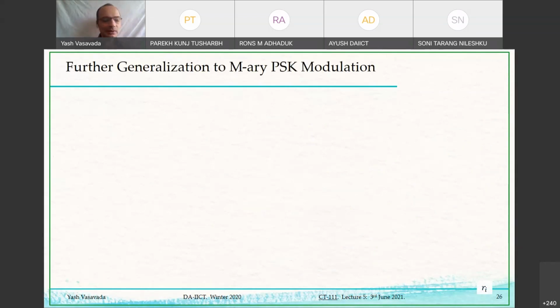So coming back to our simplified model, remember we started with BPSK. We drew the constellation diagram for BPSK. Then we went over to QPSK, which, instead of one dimensional, became a two-dimensional constellation diagram. Then we considered binary frequency shift keying, which was also a two-dimensional diagram, but now I'm transmitting only one bit at a time. There are only two constellation points. So for BPSK and BFSK, I transmit only one bit per symbol. For QPSK, when I'm transmitting a symbol over this T_symbol seconds, I'm able to transmit 2 bits. Every symbol is kind of a vehicle which has 2 bits inside it.